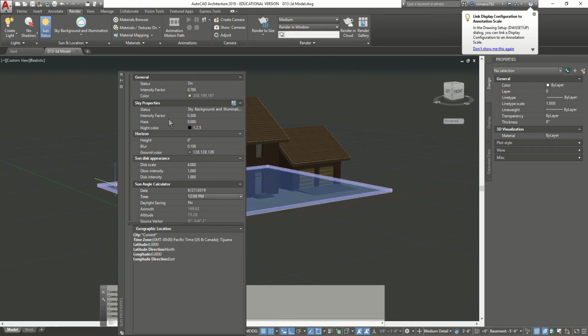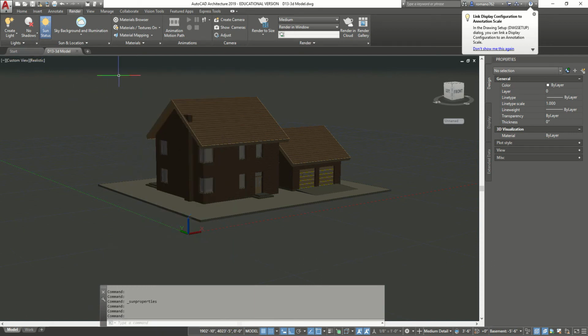All right? So all we have left to do is just put the shadows on. In this case, you notice our shadows are not on. Because in the older versions, the button was here. Now they pushed it out here. See the icon up here? So now the shadows are being pushed out there. So you're going to press close, and you're going to go to shadows and press full shadows.